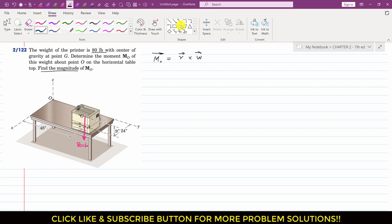So let me draw that moment arm. The moment arm can be from point O to this point G, or the moment arm could be from point O to point E. The definition of the moment arm is that it is the vector from the point of rotation to any point on the line of action of the force for which we want to determine the moment. So for this problem, let me choose this as the moment arm for this 80 pound weight. This moment arm is from O to E.